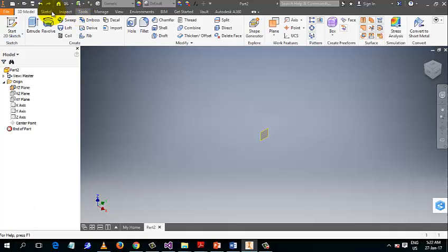So now I can zoom by, you see what I'm doing right now, rotating the scroll button on my mouse. That is for zooming. If I press the scroll button down, I can pan. You can see that the cursor is changing to something like a hand. Or you can do the same thing with this navigation bar.